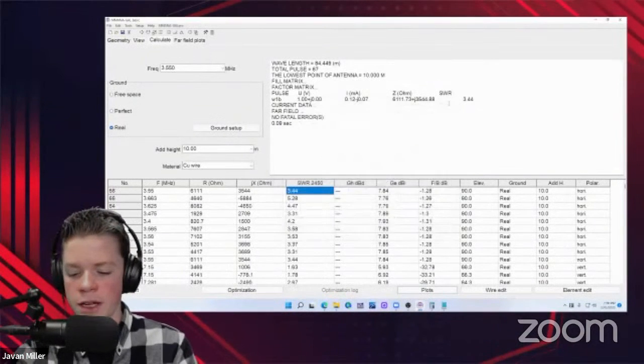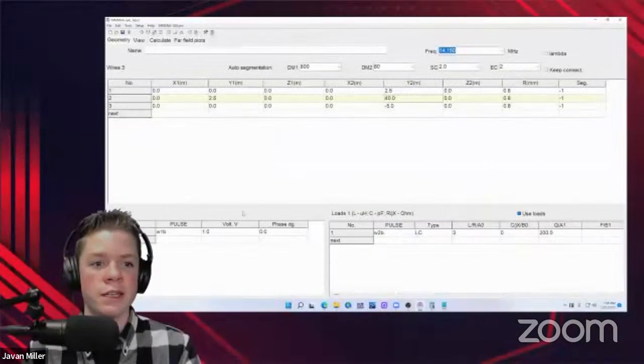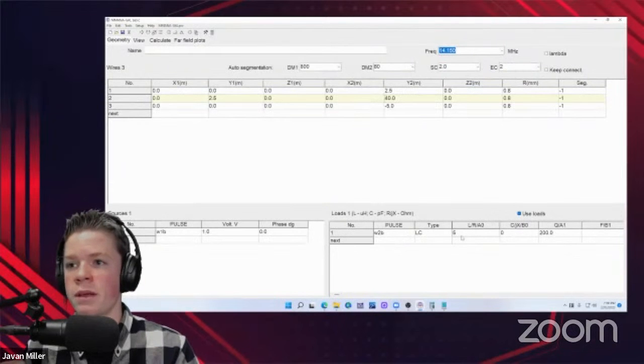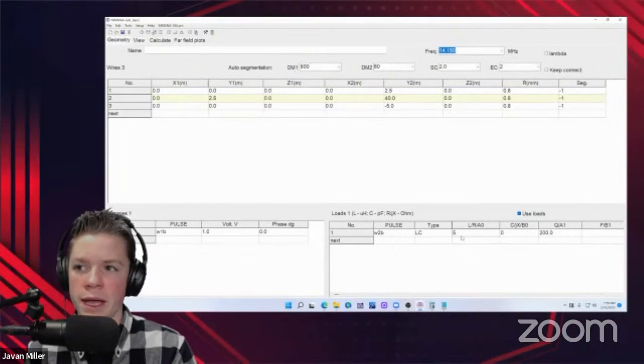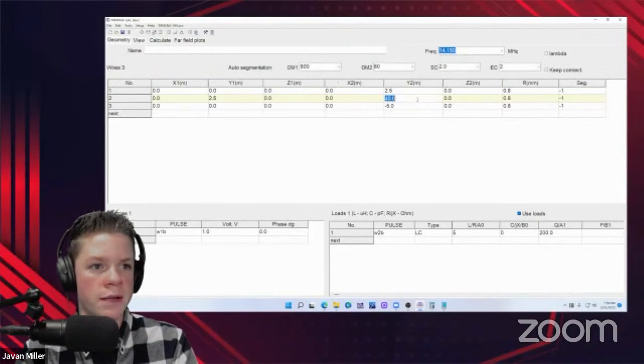I'm not sure how much time you guys have and how long we should be working on this, but we could change the inductance here of this inductor to say 5 microhenries, and that's going to have more of an impact of bringing down the resonance on the higher bands, and it's still not going to make a huge difference on 80 meters. So let me just shorten down the antenna here to just 39. Let's just go a little bit quicker here.